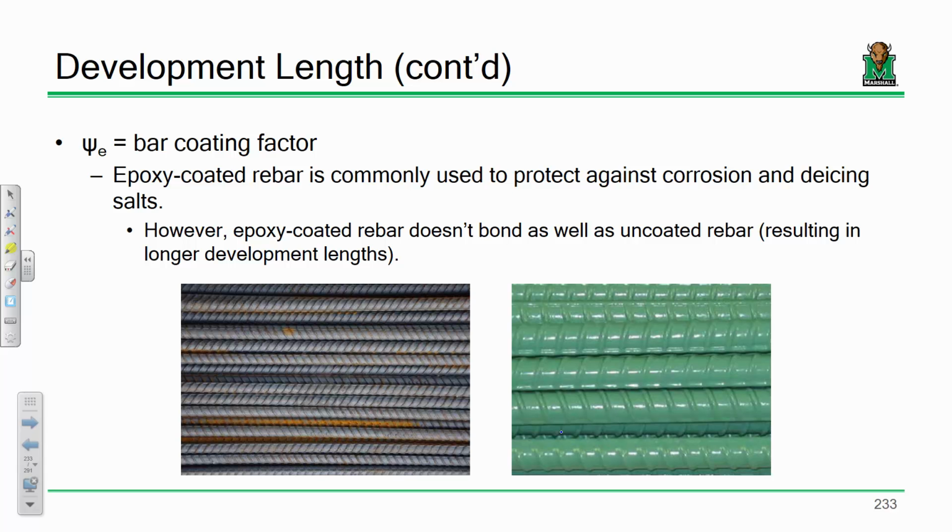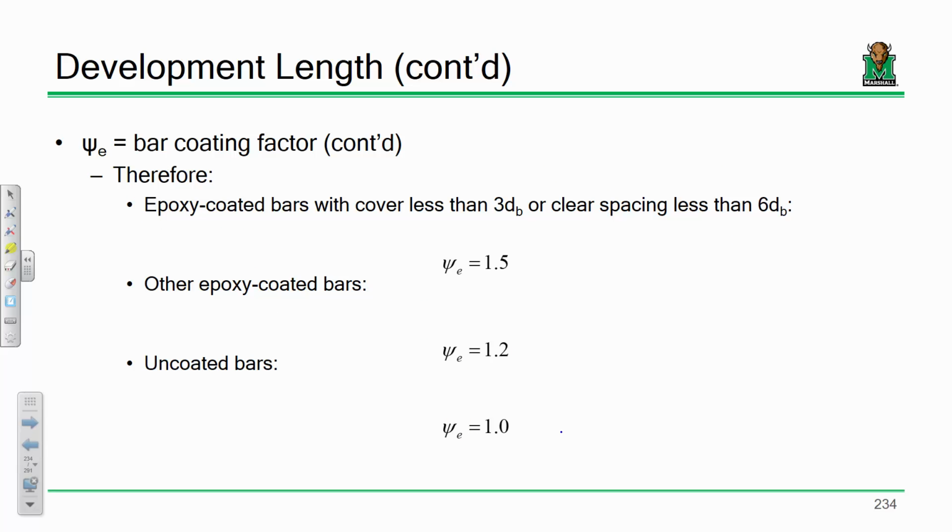If you're ever dealing with epoxy-coated bars, it jumps up. Now, it jumps up dependent upon what your cover is. Y'all remember what cover is, right? How far the rebar is to the edge of the concrete, or how far, in this case, how far the bars are from each other.